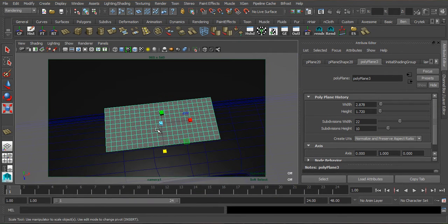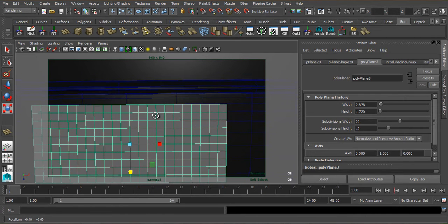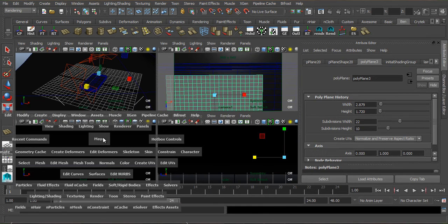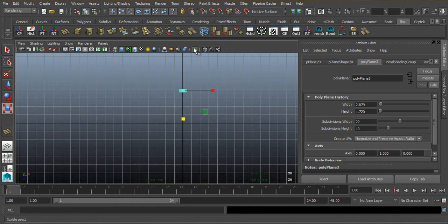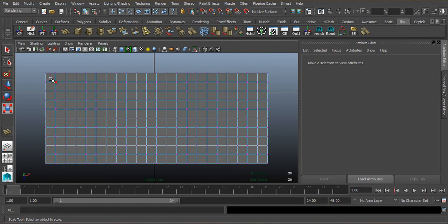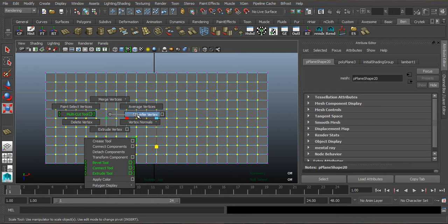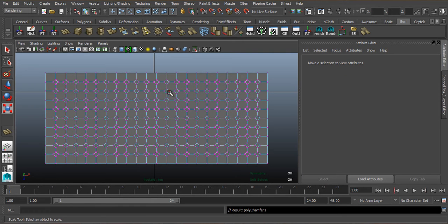Something like that will do. And then I'll just line the camera up from the top. I could probably just isolate, go to the top view, and then select that geometry, focus in on that, go to vertex, and then there's a little command here called chamfer vertex. Hold down shift, right click, chamfer vertex, and it will turn every vertice into a face like this.